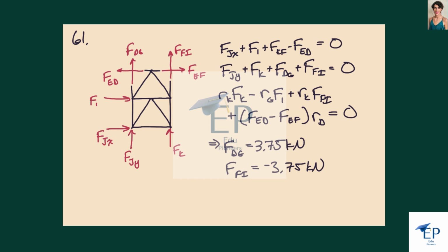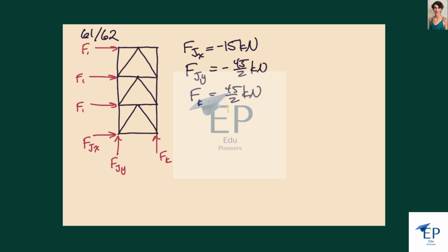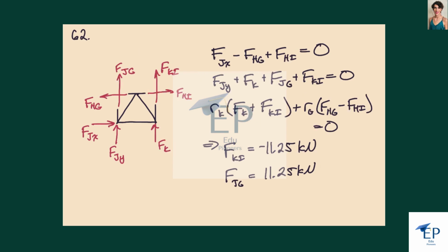In this problem, we're going to look at this truss here, but now we want to figure out the forces in these two members here. So we're going to make a cut like this, just like we did last time, but just shifted down one section. And again, we'll be able to figure out what these are, but we won't be able to figure out the absolute value of these two forces in these two members, but we'll be able to figure out what the difference is.